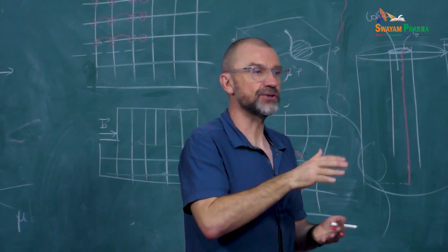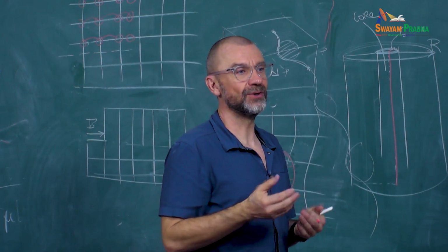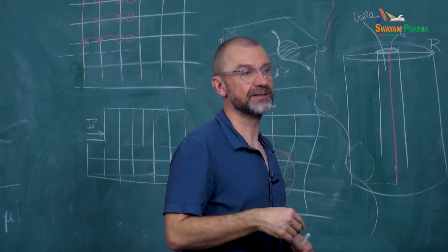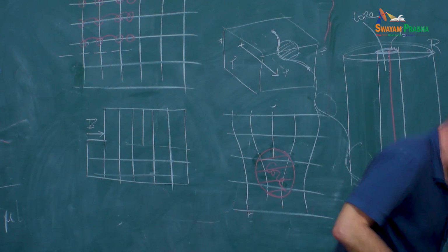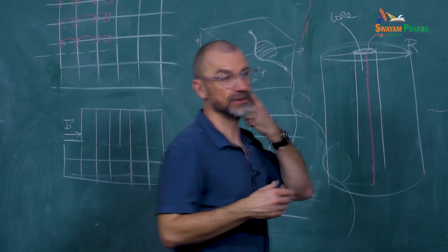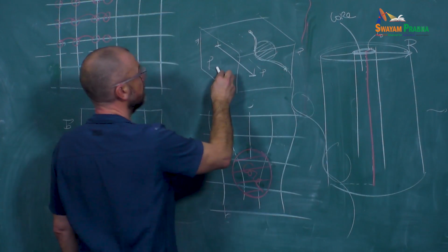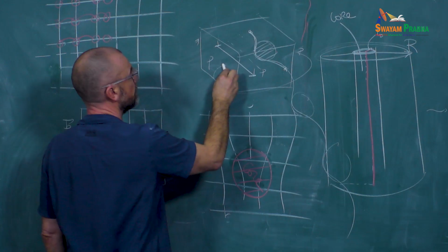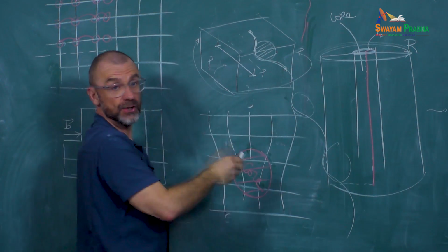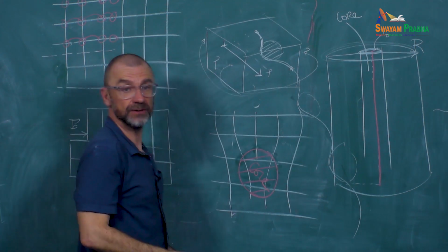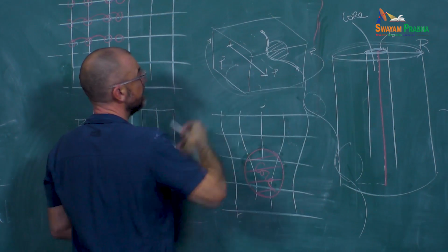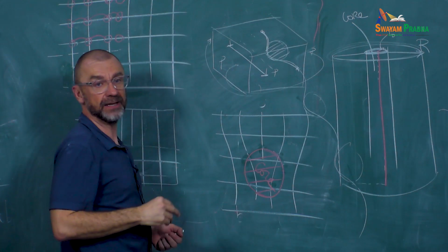And if you increase the stress until the dislocation goes away, you can measure the depinning stress of the dislocation from that defect. That was the motivation for developing these boundary conditions. So yes, it's periodic here, from here to here, and from there to there. Because of the periodicity here, you have an infinite dislocation. And because of the periodicity here, you have an infinite glide plane.